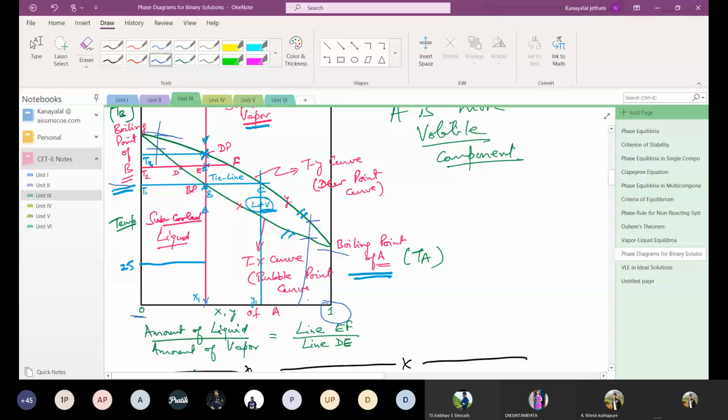because this is a vapor liquid mixture, right? ये region में जो बीच का region है, यहाँ पर almost pure liquid है, यहाँ पर almost pure vapor है, but इस दोनों के बीच में it is a mixture of liquid and vapor, right? If I take this, it will give me liquid of composition X and vapor of composition F in this region.